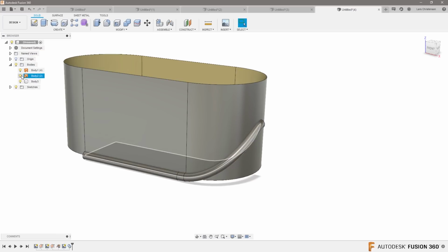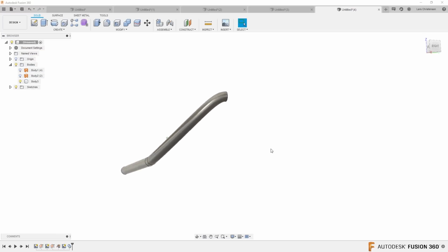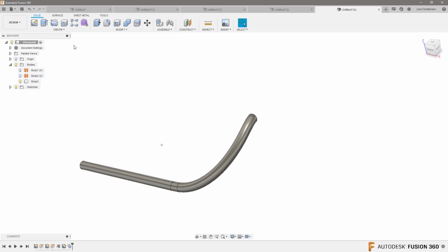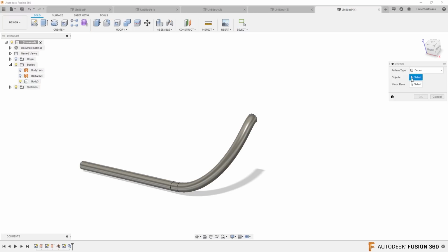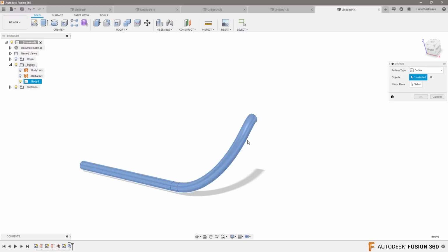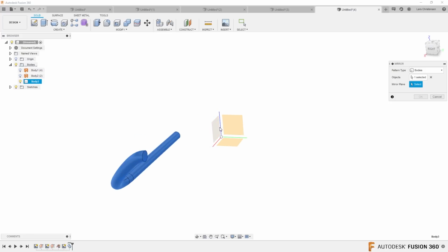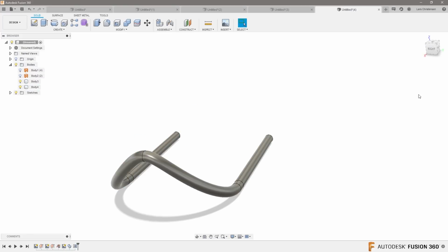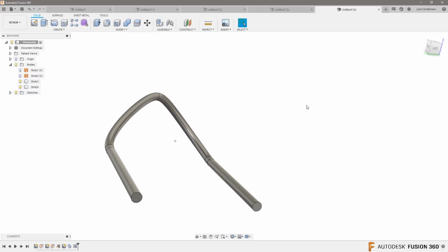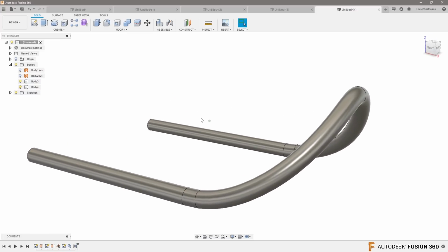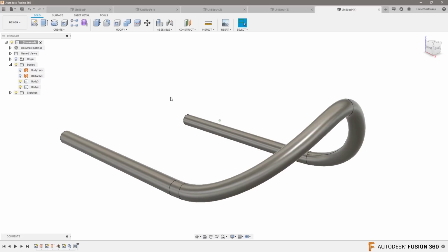And if I turn these surface bodies off, now look what I got, using that development to do this. So now you could go in and do something like a mirror. And if we select this body, and we mirror that over this plane here. And now we have maybe not a motorcycle frame, but we somewhat got that development there.